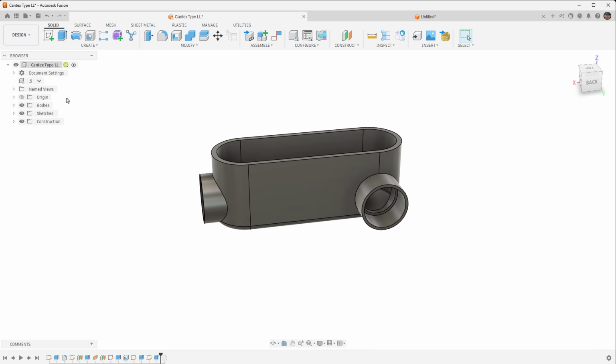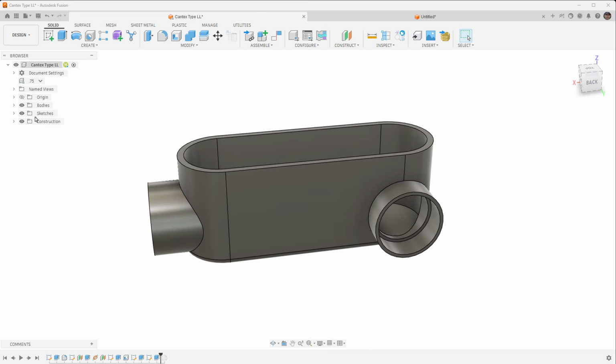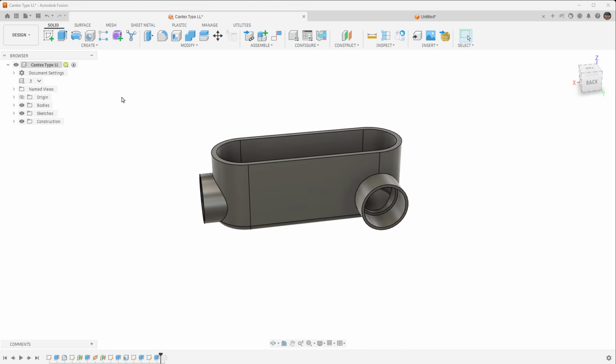An example like this is generally going to be something that is controlled by dimensions and needs to be updated to different sizes, different families as there would be. So when we look at something like this, we have various dimensions that need to change to alter the size of the part. If you're modeling this in a professional sense, typically it would also have draft. There's a parting line right in the middle of each of these inlets. There's going to be screw bosses on the inside.